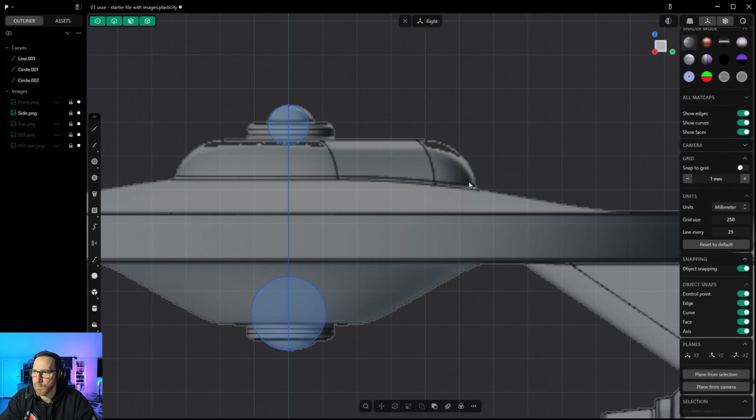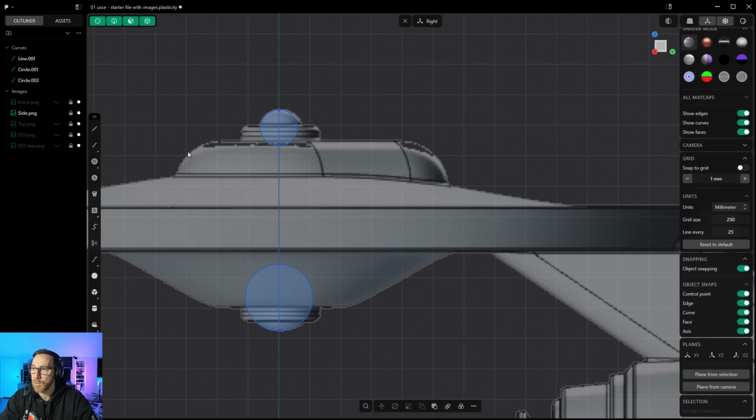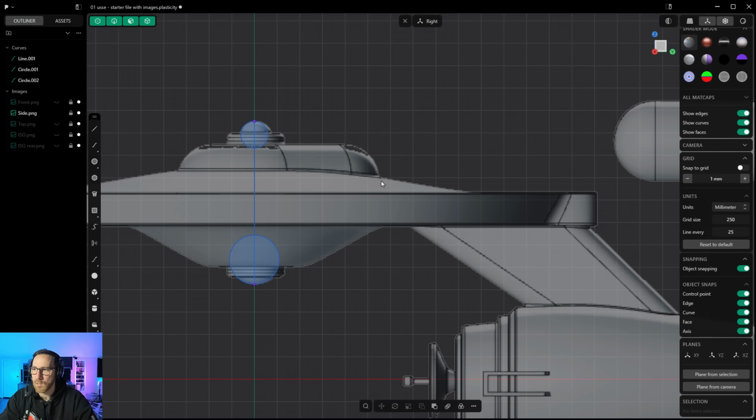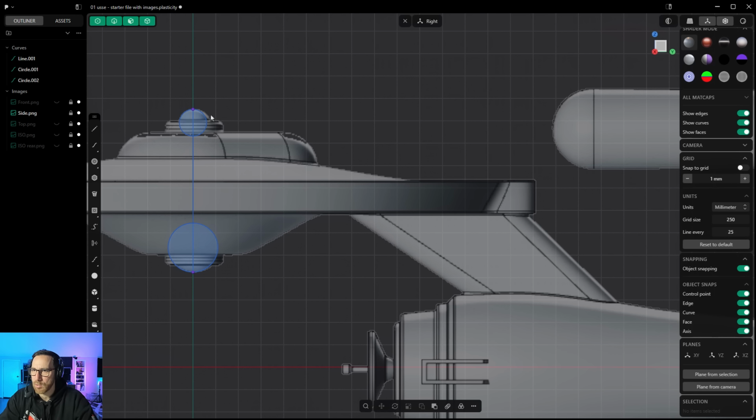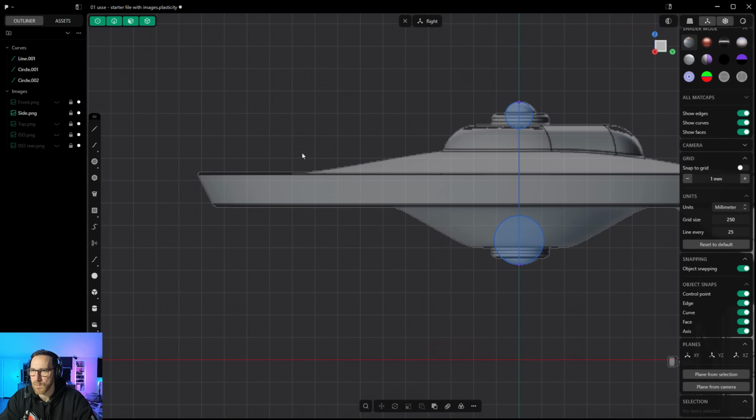This main portion of the body is something that is not going to be able to be captured in the revolve, but everything else can be. And so we're going to use a couple of line tools and then a couple of splines or potentially bridge curve, and then we'll use those to finish off the shape. And so one thing that's going to be a little tricky, and I'm just now realizing this, is generally I like to work to the right, but this piece here that bumps out is not going to help us. So we're going to actually work to the left.